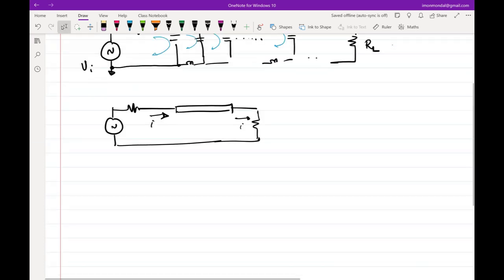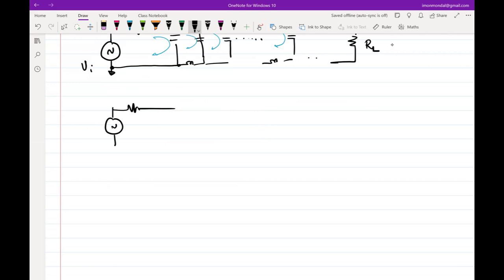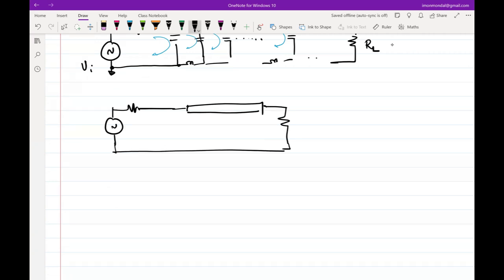Fine. So we'll stick to the conventional transmission line picture. The assumption is that there is a return path somewhere in between. So that's why the ideal transmission line picture should be like this. There can be a return path from between, right? But we are only treating the transmission line as a delay element, which is okay, given that it behaves like a wire, or like a simple delay element. Let's say it has a characteristic impedance of R0, which is real, and RS, RL. I will simplify our life.